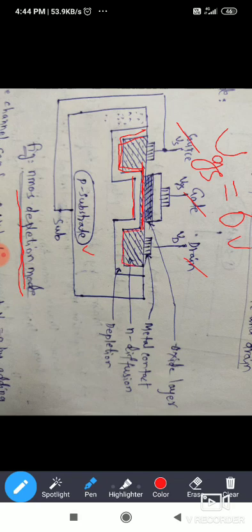Here doping means diffusing the N type material at a particular temperature. This one indicates the depleted area interface. When we apply gate to source voltage greater than the threshold voltage, electrons flow through the channel from source to drain. We will get current at the output terminal ID.